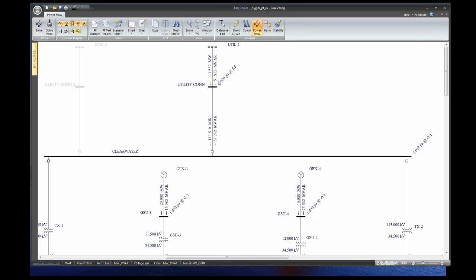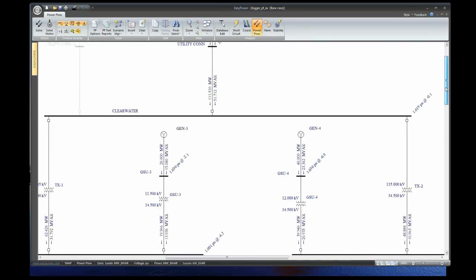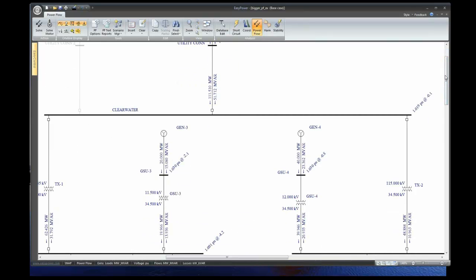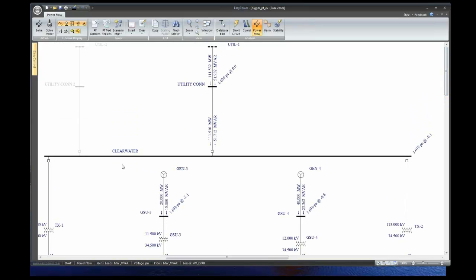So this made a sizable increase because I've got additional voltage here, so that's going to create more VAR flow down into my system. And that VAR flow gets used up in the inductances of my system, like across the transformers and my cables and anything else that has inductance in it. So the real power doesn't change very much. It changed a little bit because the current went up.